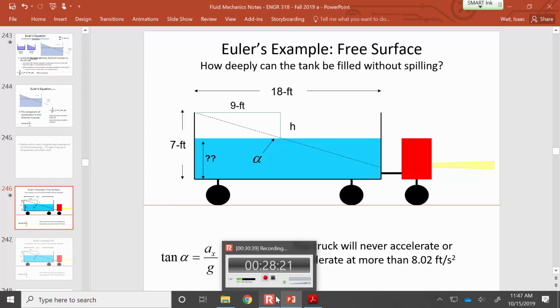Right. So if we're going to draw a little picture of what kind of system we'd apply convective acceleration analysis to, maybe it would be a nozzle where the cross-sectional area is either increasing or decreasing. In this case where it's decreasing, you had slow-moving water and then fast-moving water, because the same flow rate in liters per second was forced into a smaller cross-sectional area. That caused the velocity to go up. So velocity changes with respect to position.